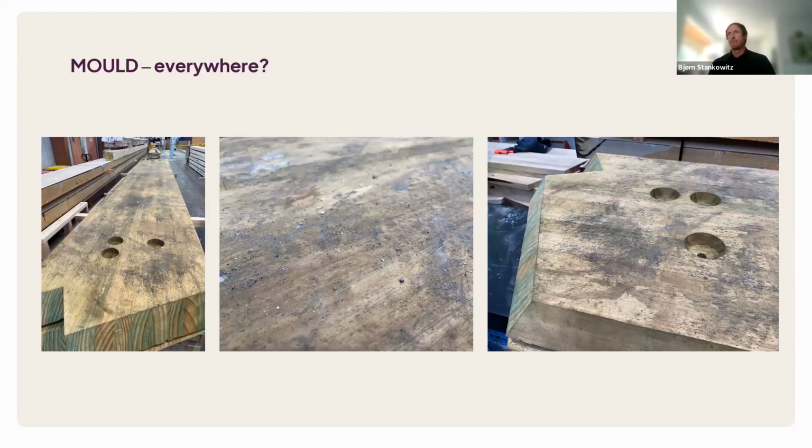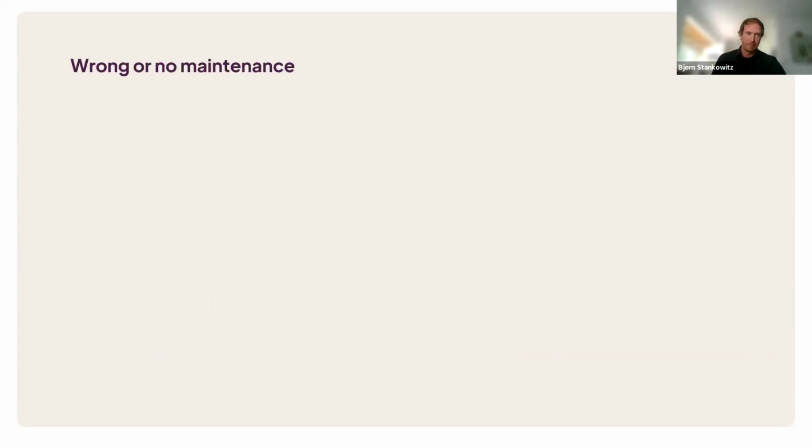And then there's the question about mold. Mold is everywhere. Mold is in New Zealand. Mold is in the world. It is in fibers, in spores, floats with the wind. And if it gets on your timber, it starts to nest down and discolor your surface, which is a really downturn when it comes to the end of the project, because stained timber, most of the times beautiful glulam is left visible, has to be sanded off, and that takes a lot of time, obviously.